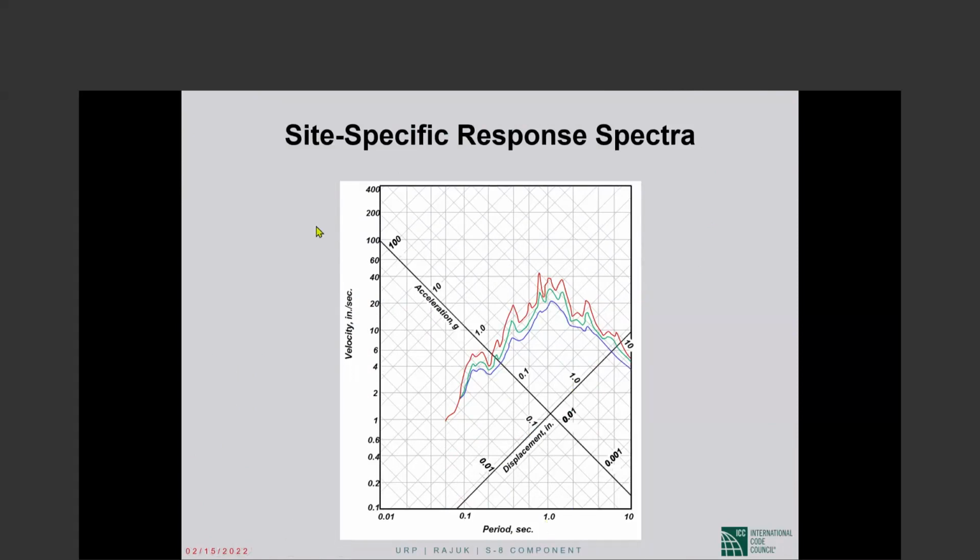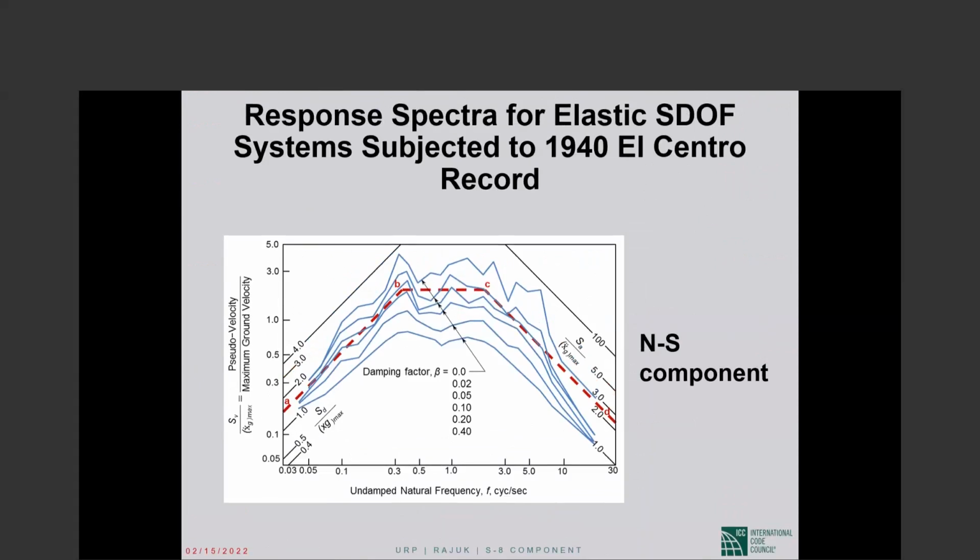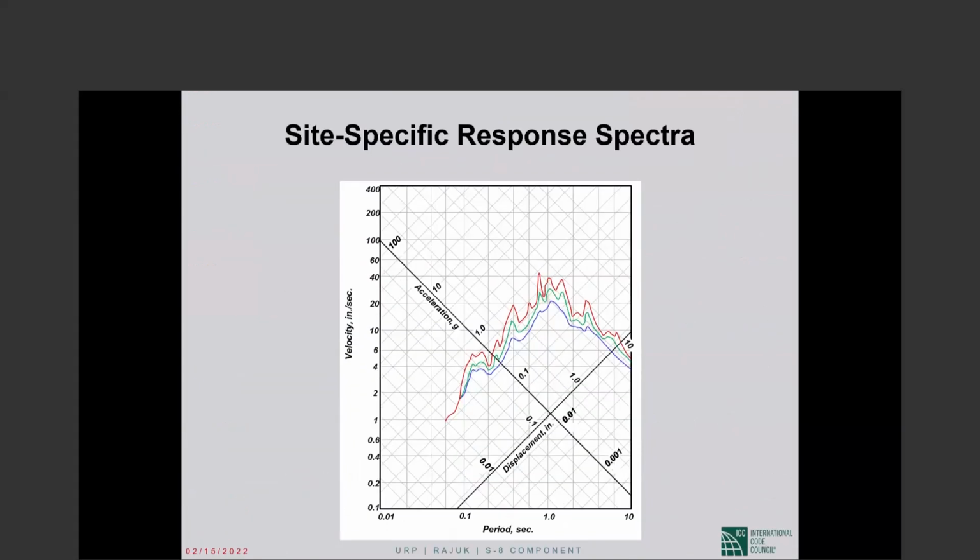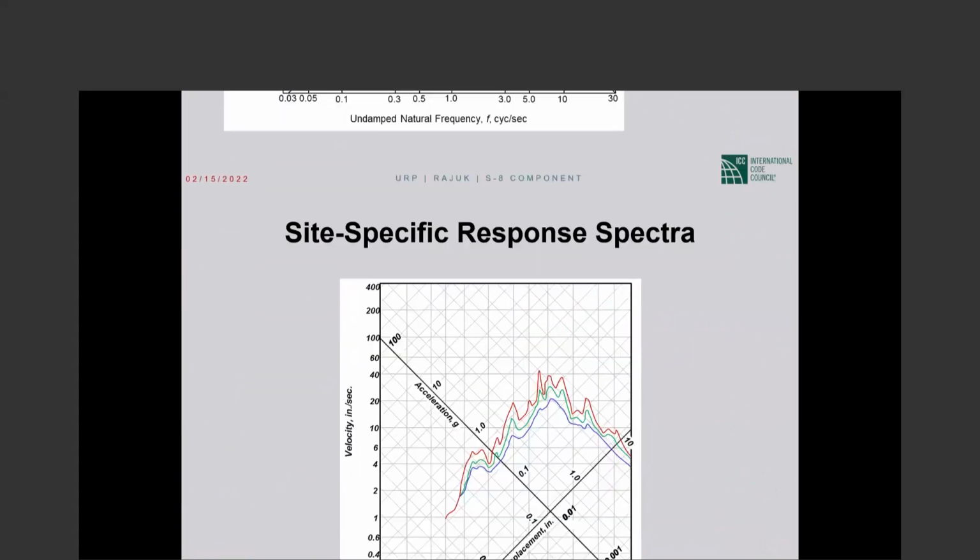And this diagonal is the acceleration scale. I hope you see what I'm pointing to. Okay. Anyway, so this plot is not very different from this plot, except we have only 3 amounts of damping, and I have period on the x-axis, not the frequency.